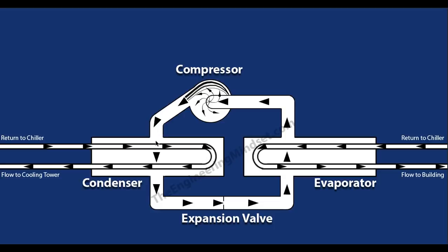The refrigerant comes in and condenses along the tube wall. It does not enter into the water. It just condenses on there and continues flowing through there, pushed by the static pressure until it hits the expansion valve. The expansion valve is just expanding that refrigerant, giving it a greater ability to pick up heat when it gets into the evaporator there. So these are the four main components and the three main circuits you need to know about. They will appear in every chiller, of all types, sizes and shapes.